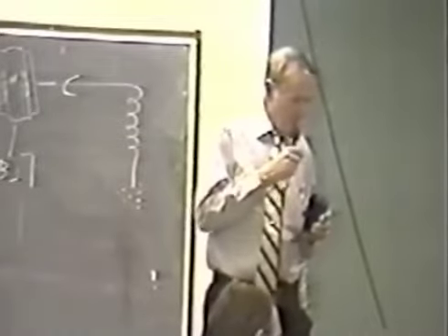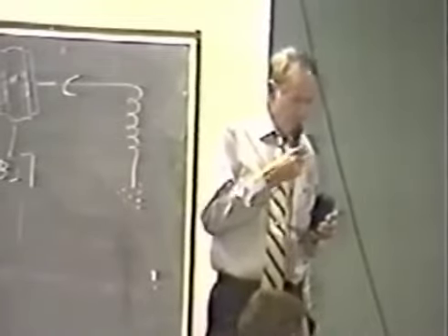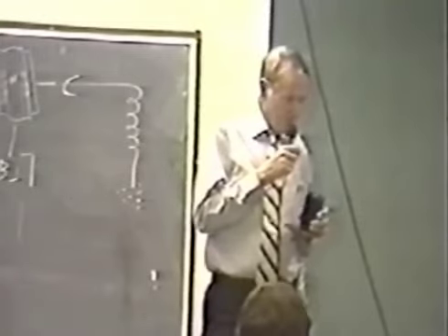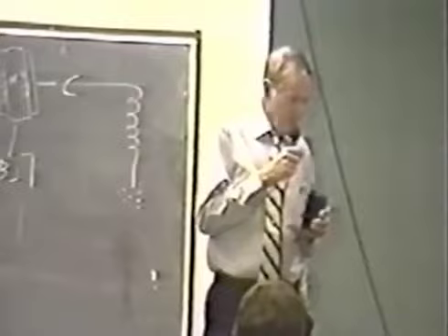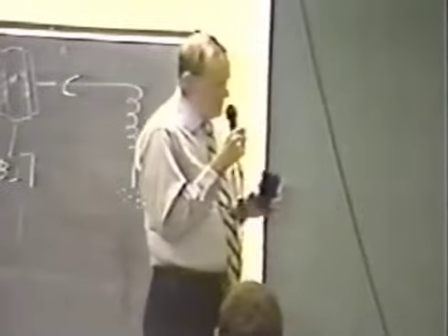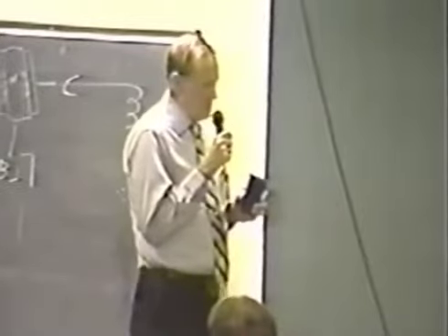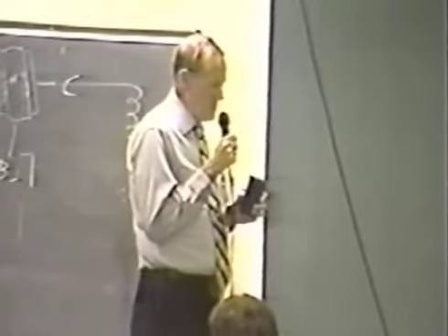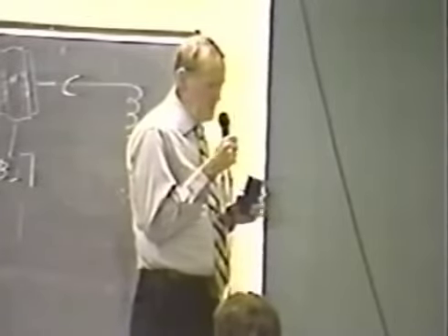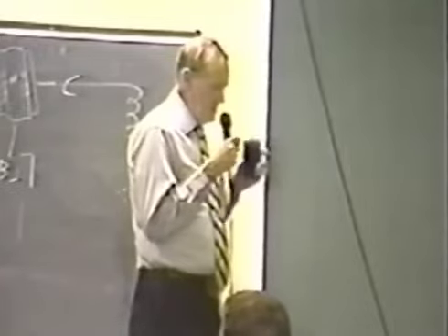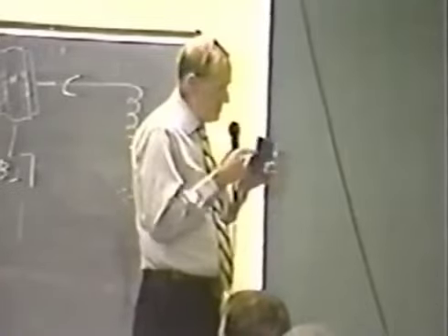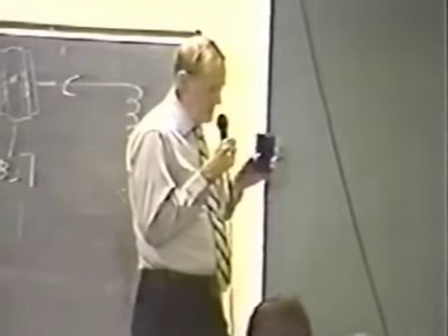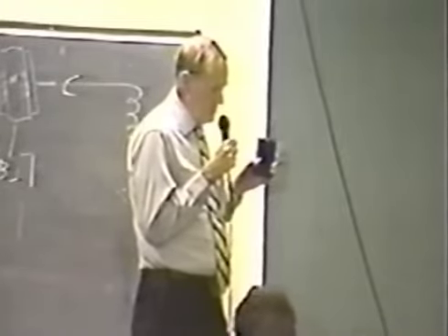What are the possibilities of voice modulating the signal coming out, using it as a transmitting device, receiving communications? Very definite possibility, but one has to have a detector in order to demodulate, in order to use it as a useful transmission of intelligence device. You want to have 2 links, a transmitter and receiver. This is a transmitter only, and we do not have any modulating techniques on this. It is strictly a square wave generator driving it.